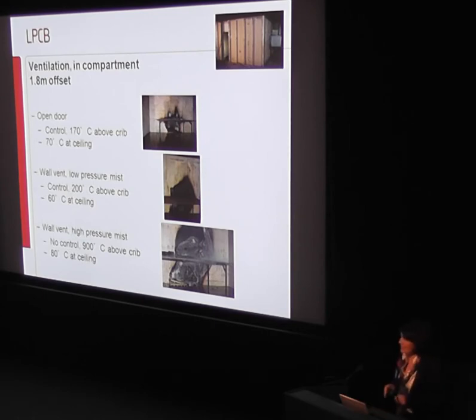When we carried out ventilation in the compartment, this was a much better result. Not only did you interrupt the burning of the fire, you also get circulations within the compartment, which arguably keeps some of the mist in place. So when we carried out stylized setups within the compartment, we did get control at the 1.85 distance away, and we had the crib beneath the table as well.